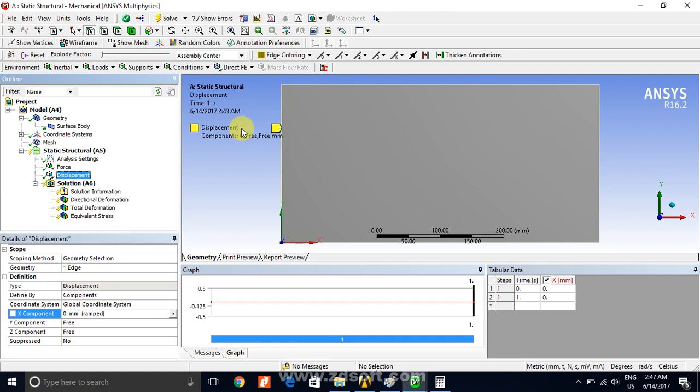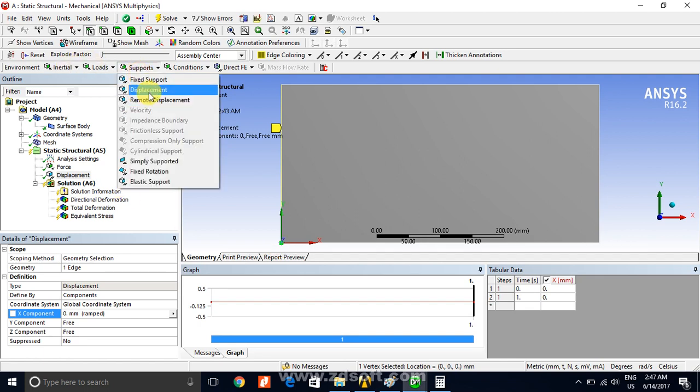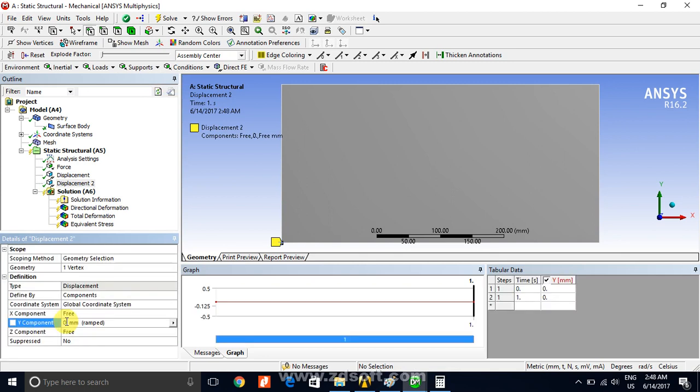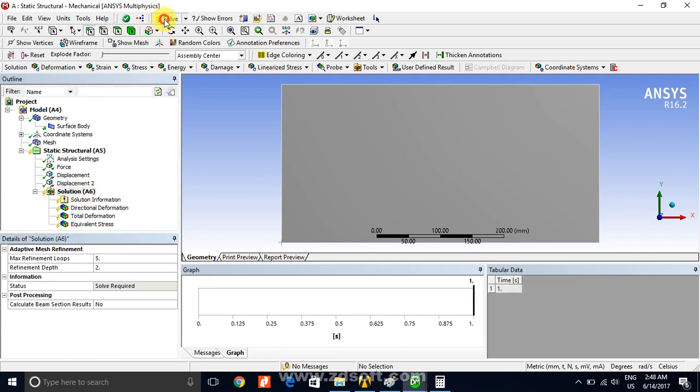The boundary condition is also a vector quantity, so it must be in the same direction as this force. If no force has been generated perpendicular to this direction, why would we apply a boundary condition in this direction? So I think you have understood that we have made a mistake. We should not apply the boundary condition in this direction. If you solve this problem, the FEA will not solve because this matrix would still be singular. So to avoid the singularity, just take one point and fix it in the y direction, and solve it.